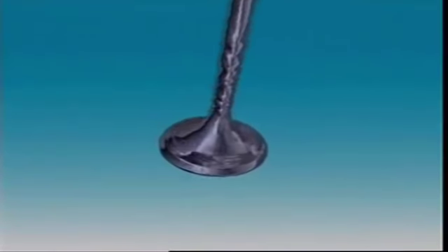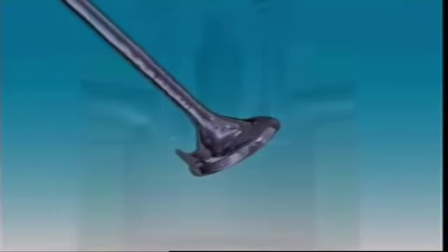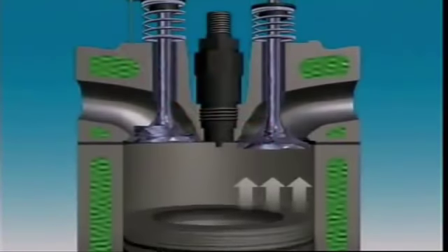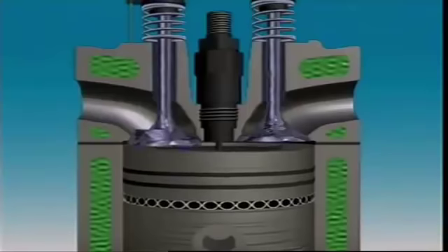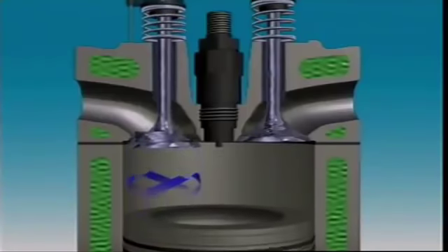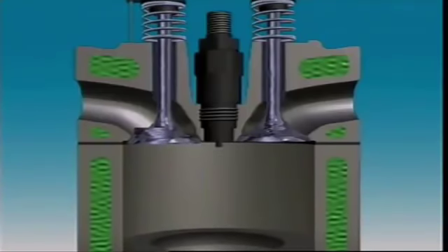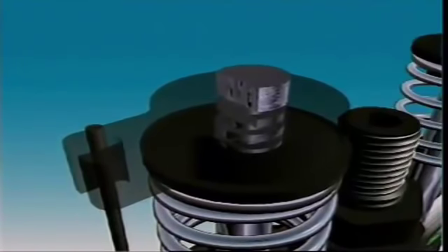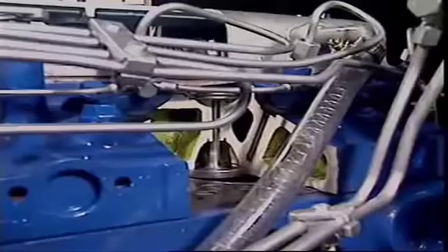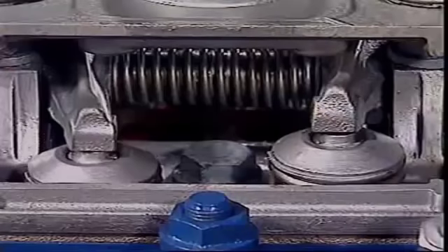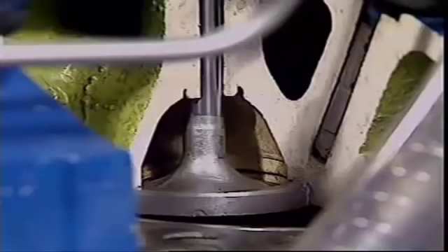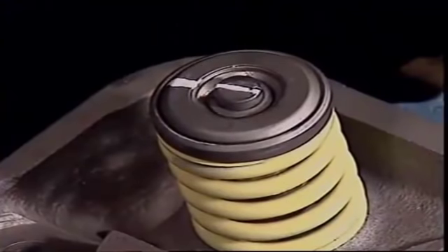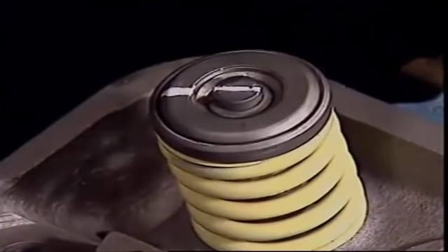On some diesels, the inlet valve has a shroud or mask on the back of the valve head. This is designed to cause turbulence in the incoming air. The position of this mask is critical for best operation, so the valve is pinned to prevent it rotating. If the rocker arm is slightly offset to the valve stem, it can help this rotation. Some engines even use positive valve rotators.